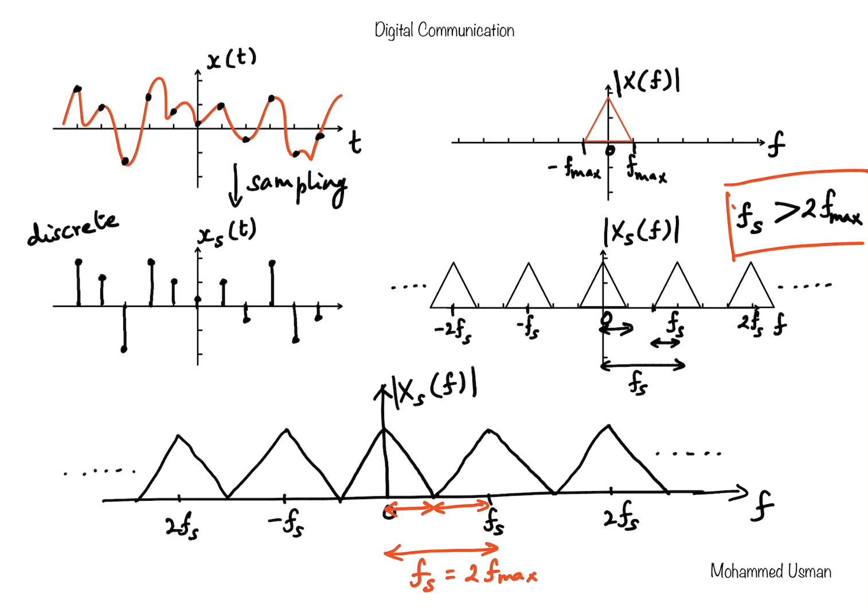So that means the higher frequencies are moving on to lower frequencies. And even in this case, where the sampling rate is exactly equal to the Nyquist rate, there is no problem, because even though the replicas have moved inwards, they are not interfering with the previous replica. They are not overlapping with each other, and therefore they do not cause any distortion.